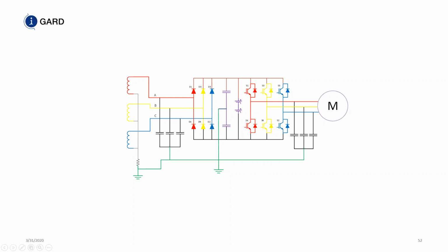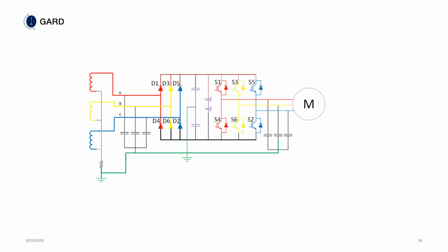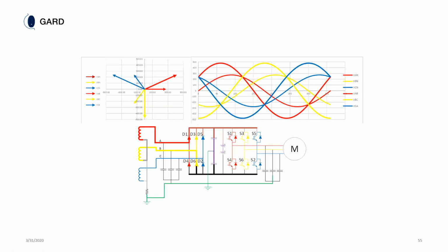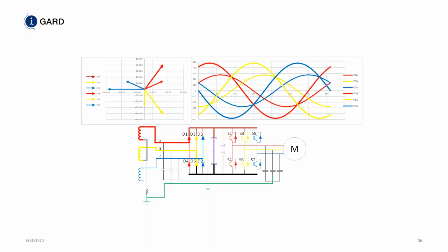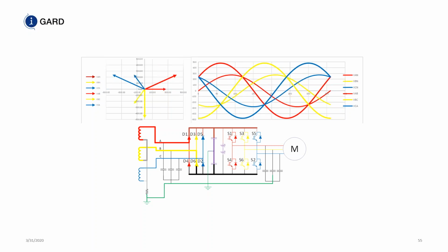If you look at your screen right now, we have a three-phase system with a single VFD on it. What we can see is when you have a fault, the diodes are forward biased only when the voltage on A phase here, sorry, you can see that diodes 6 and 1 are forward biased in this situation, so they conduct.